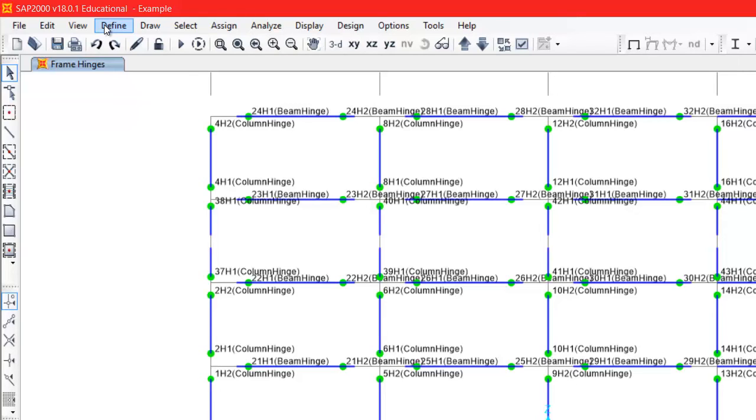You are just given all the loads, and then you are told, just sum up, multiply by the area, and so on. But you have to be careful, because some loads are given in pounds per square foot, PSF, and others are in pounds per linear foot, like the weight of beams or columns per linear foot, while area loads are per square foot.